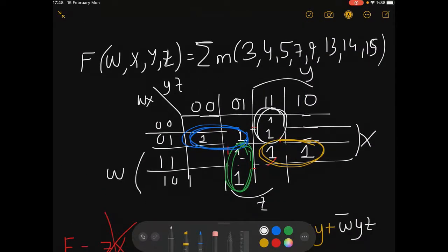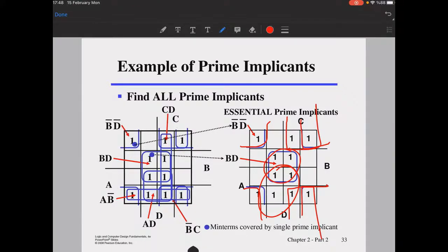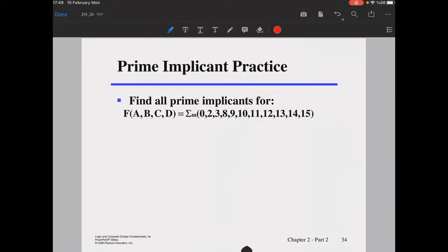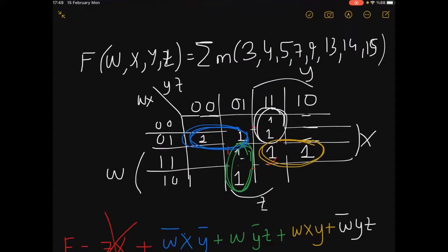And no need to put the largest square in the middle. That's why the solution looks like this. So this is another detail with the K-maps for finding the prime implicants here. It's an important concept. That's what the algorithms are using as well. Computer-aided tools are doing it as well for the sake of simplification. Now let's find all the prime implicants for this example. Okay, let's do it. For this purpose, I need a fresh board.